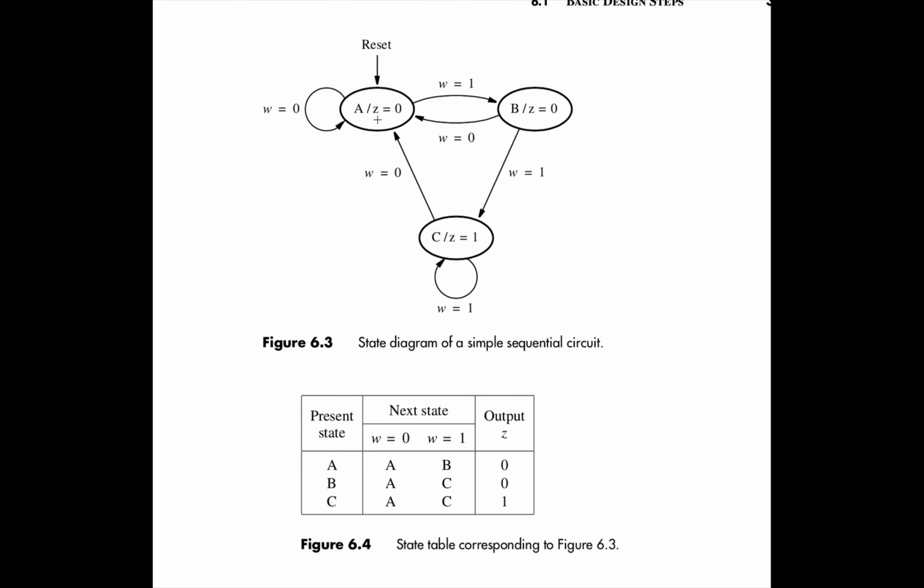Good. And then one thing that is very important when you're building state machines is this guy, reset. From now on, anytime you build a state machine, you need to have a reset. Because once you hit reset, that tells your state machine which state to start with. If, for example, you didn't have this reset, and if you just had A, B, and C, then what will happen is that it might work in simulation, but when you power on your device, you don't know what state you're going to start with.